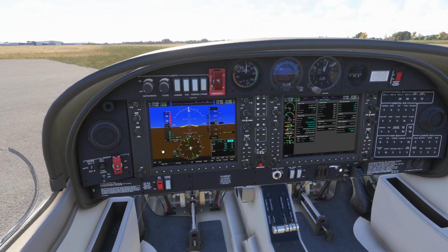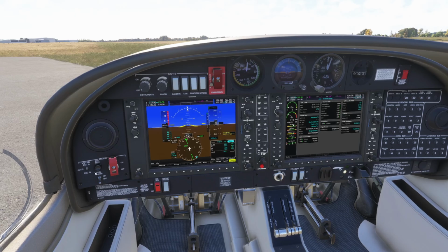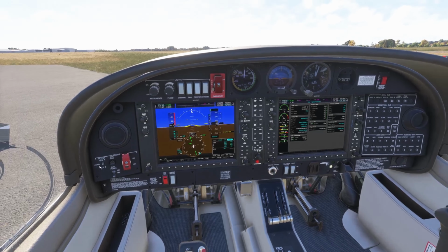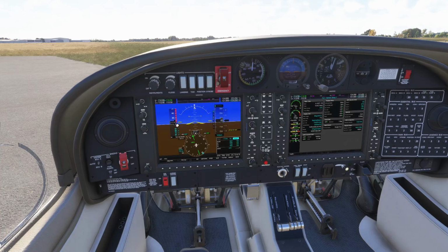So now we need to test the voter switches, so this will change it from ECU A to B. So we'll change it to A. You should feel a little jump. T's and P's still in the green. And I don't think you can switch it to B, but you would turn it back to B and it would do the same thing, it would jump a little bit. Back to auto.